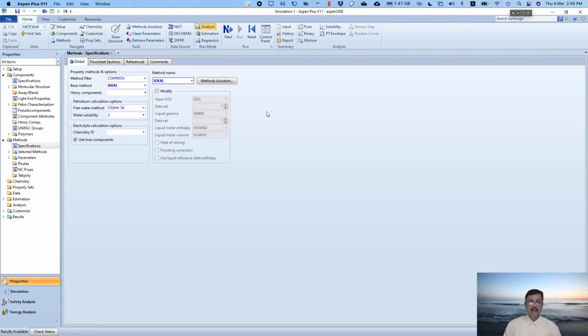Yes. Now you can observe over here this binary analysis. Here you can generate TXY and PXY diagrams and free energy of mixing curves for a binary system. So we will try to find out the vapor-liquid equilibrium for the benzene-toluene binary system. Let us click over here.